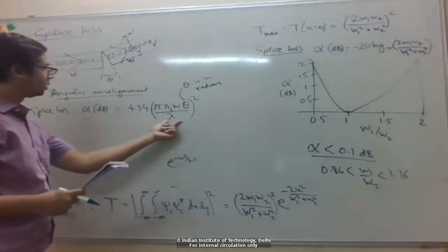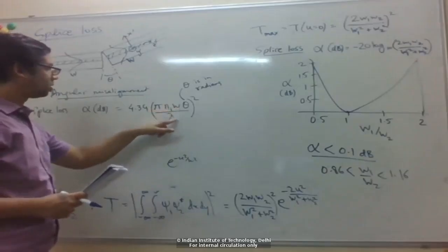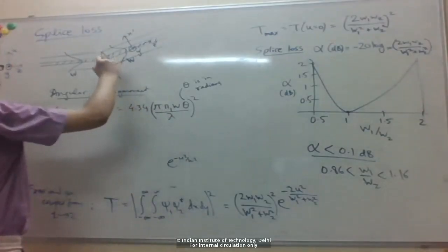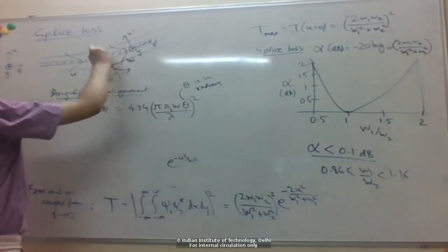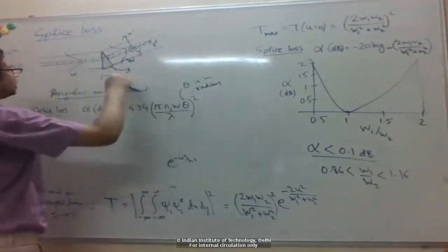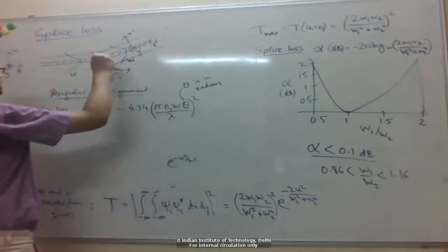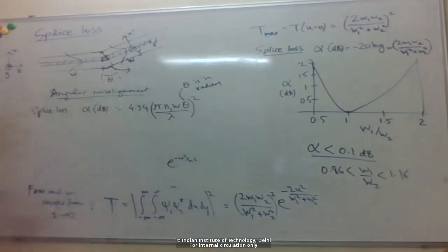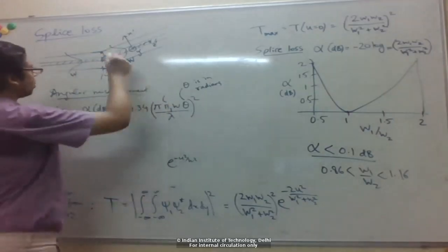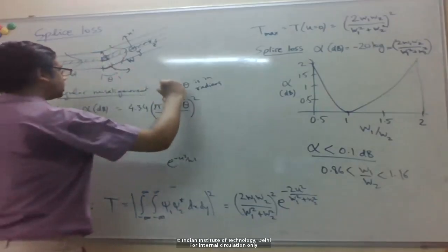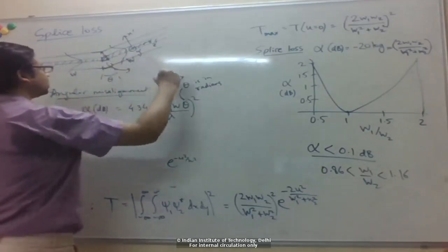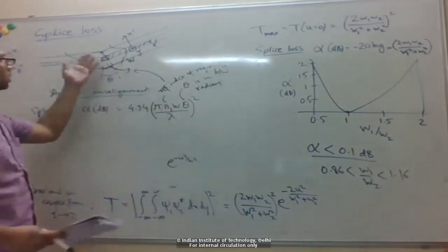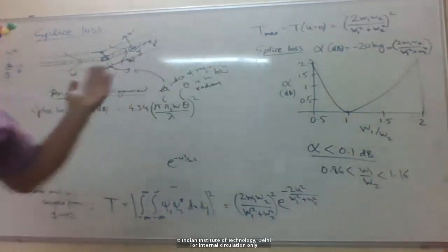Now the wavelength also factors in along with the spot size, so the ratio of spot size to wavelength is important here. And N1 is the refractive index of the medium in between, in this gap here, which you have to assume to do the calculation. But as I said, in the splicer you fuse it, so this in-between region also just becomes glass. So we can just use the refractive index of the fiber. For a splice, that's just the glass refractive index.